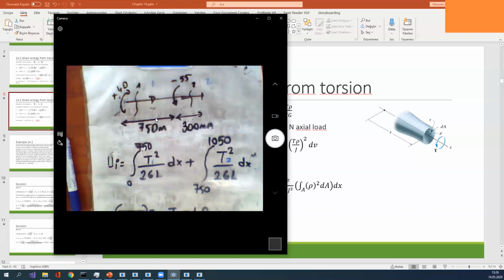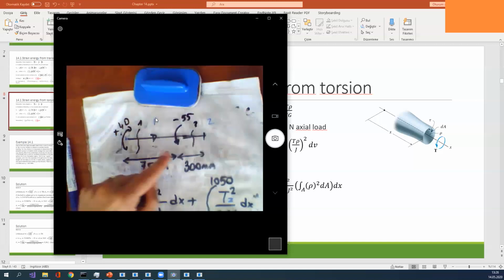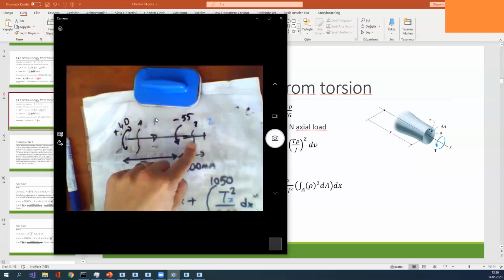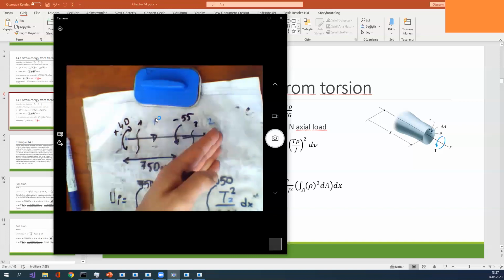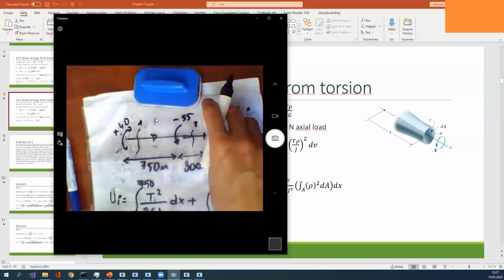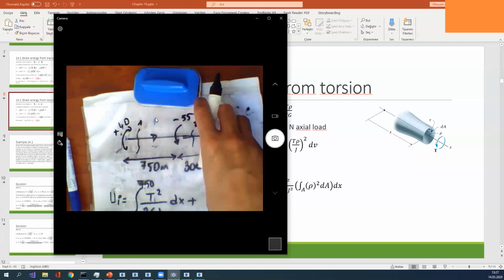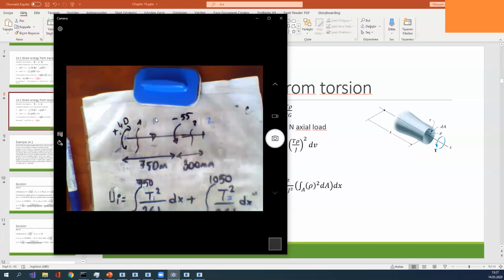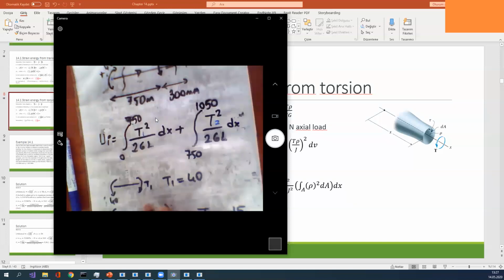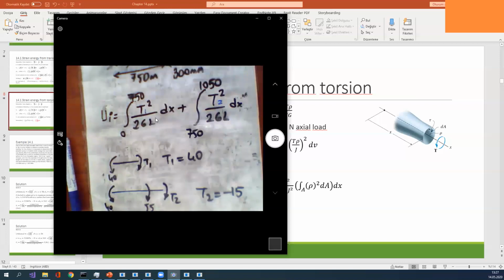Don't write 55, because if I want to take a cross section, I want to add this. Don't start with the right side, because this right side is a support in here. Total support is minus 15. If I start from the right side, don't forget to put the reaction torsion force in here. I want to erase this part because I already calculated T1 and T2.